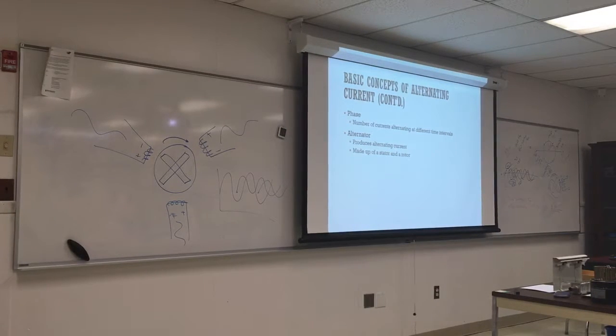So you always need something to push it. Usually that's a capacitor. Capacitor charges, and then you push it off center. The best example of that is you go to a compressor outside. You turn it on, and it's humming. You try to push the fan with a stick, and it starts running fine. You just knocked it off balance. At some point, you get to a point with plus and minus at the same time, the same amount, and it's just going back and forth. You need to go off balance to start the cycle. And that's why we usually need capacitors to push the motor out.